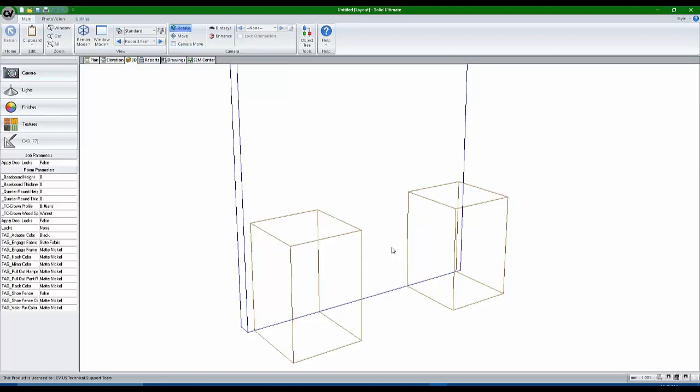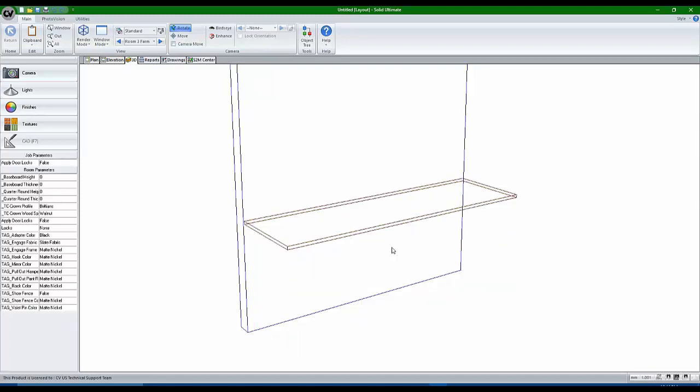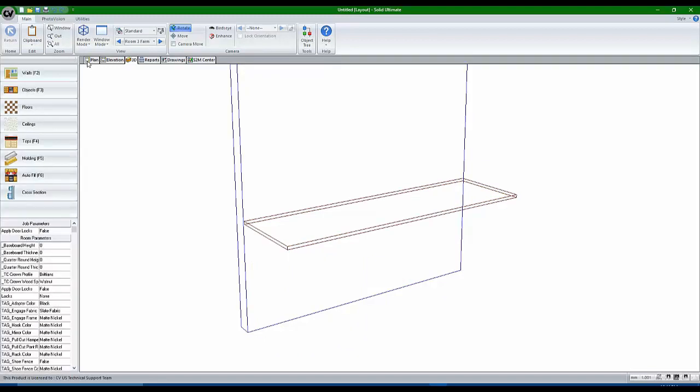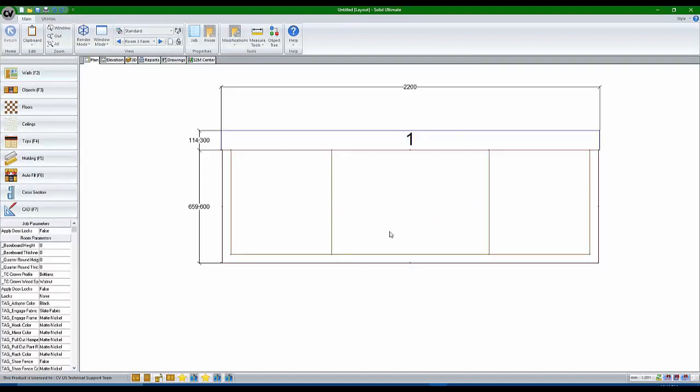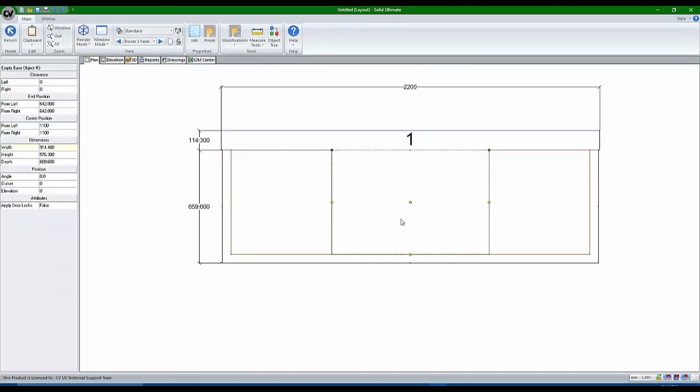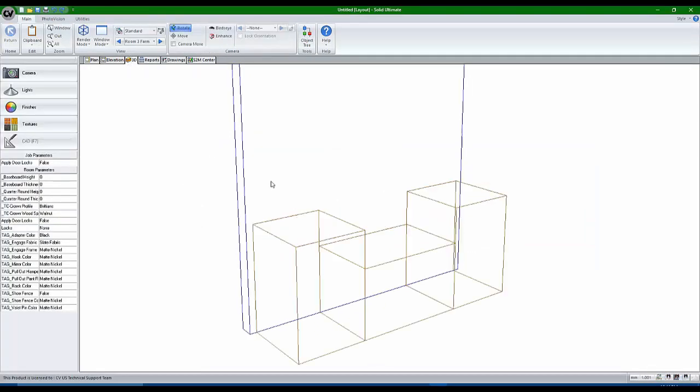It would be 900 millimeters, however wide this is, but it would also be 300 millimeters shorter at the top to allow for the butler sink to fit in that space. But if we do that and we auto build our countertop, then the countertop will only put a top on either side. So what we're going to do is go back to this, and I went ahead and undid that so that we get this cabinet back in.